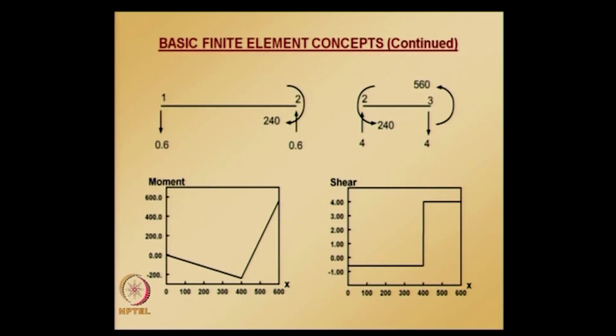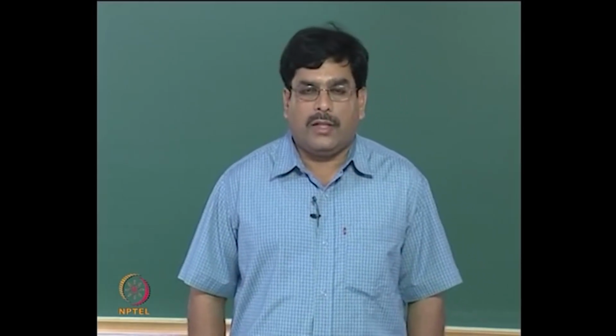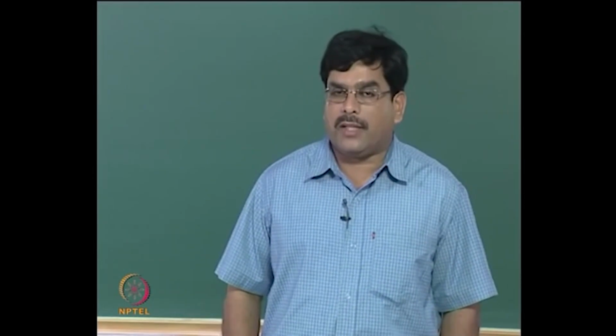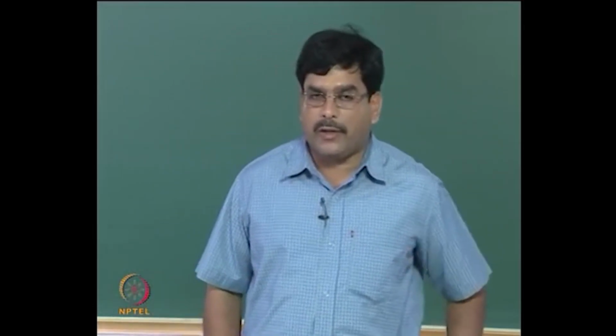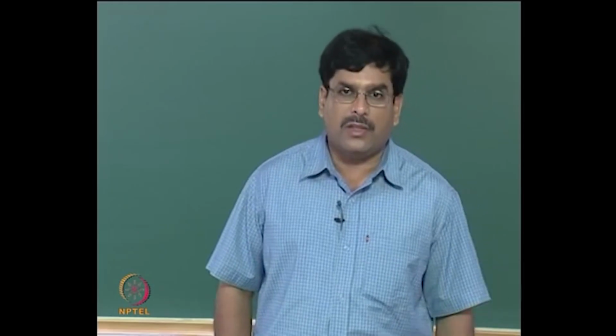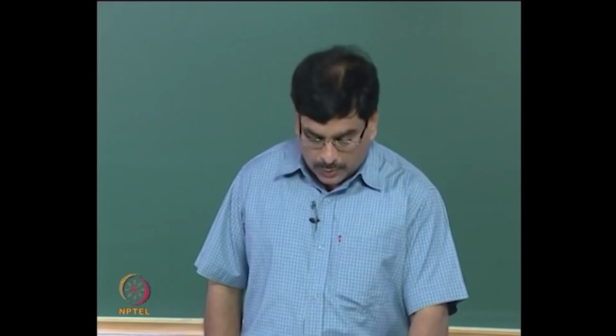Whereas if you apply those element equations to non-prismatic beams, that is, beams in which EI is not constant but varies along the element length, or to beams subjected to distributed loads, it may not be accurate and there will be some error in the solution.